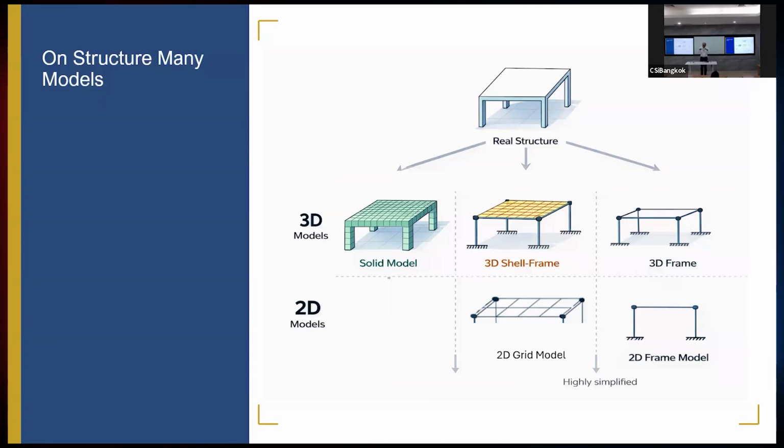So they divided the structure into 2 separate parts, deck separate, use P2, and frames separate, use P1. Manually combine the results together. Transfer the results from deck to the frame, analyze the frame. And that's how we used to do earlier. So depending upon the tools that you have, depending upon what you want from the structure, you can choose any one of those models, each with its own data, limitations, and all.